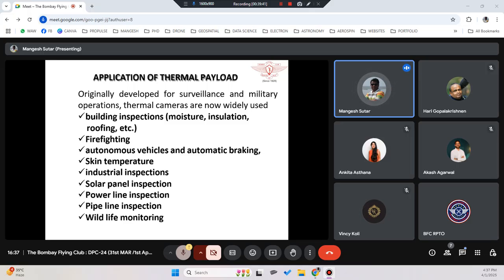We do not know anything about the pipe from outside, but a lot of times we have seen the pipeline used to burst. There would be some leakages. What happens is that when water is flowing inside the pipelines, the outside of the pipe, the metal, is subject to the outside temperature and atmospheric conditions, whereas inside it is completely cold, with continuous water flowing. So a lot of times corrosion used to happen. As the water moves continuously inside the pipes, in some places there used to be very heavy corrosion. Okay.